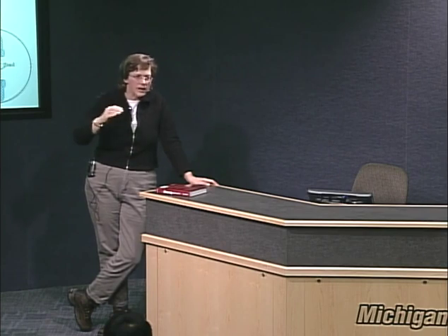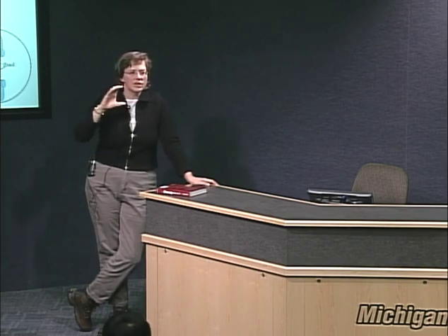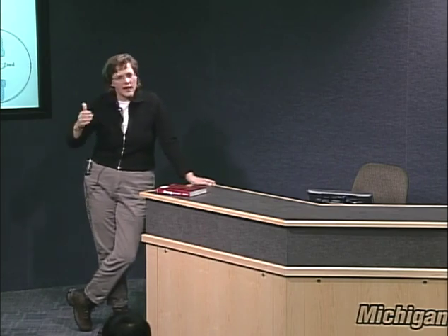You could think of it like ASTM, if you've heard of ASTM standard tests. But you know what? The reason there are so many rules to an ASTM test, if you have any experience from your co-ops, this size material in this size die at this size rate at this prescribed temperature, everything is prescribed. And the reason is that the natural world is so complicated. If you use a different shaped die made out of a different material and went at a different speed, you'd get a different result. So you need to hold everything constant and compare apples with apples.